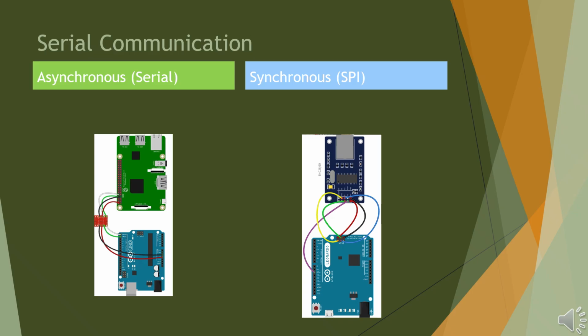Both devices can communicate using UART, which transfers data one bit at a time over two lines: TX, transmit, and RX, receive. The Arduino Uno provides these on pins D1, TX, and D0, RX, while the Raspberry Pi uses GPIO 14, TX, and GPIO 15, RX. Because the Pi operates at 3.3 volts logic and the Arduino at 5 volts, a logic-level converter is essential to prevent damage and ensure reliable communication.